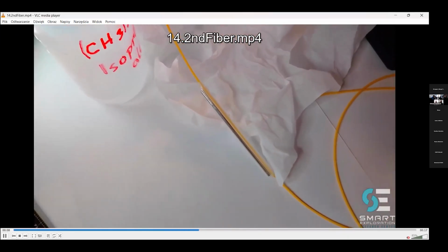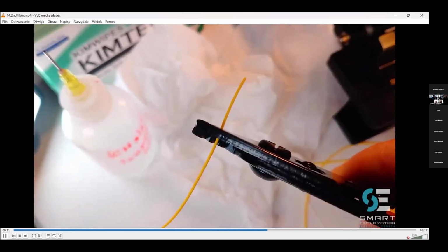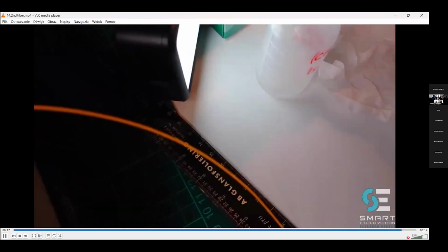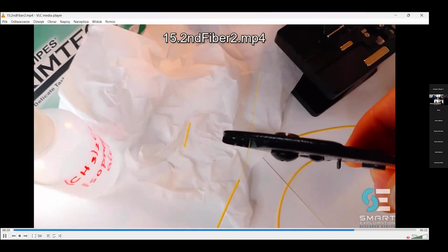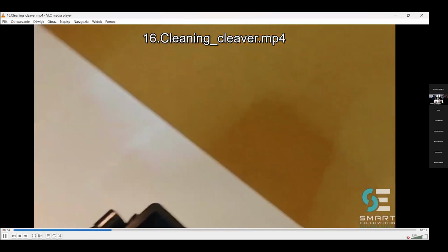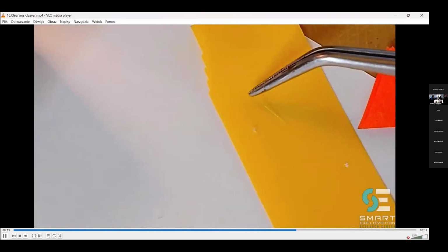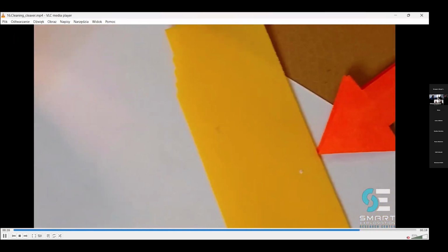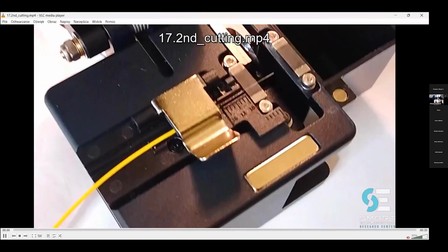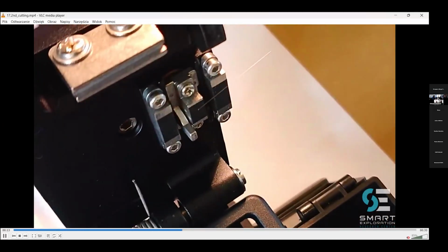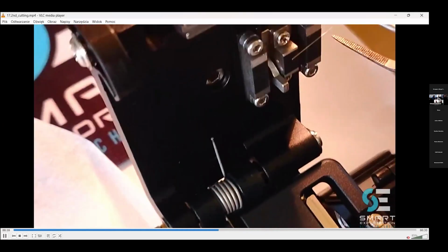And for the second part of the fiber optic that we want to splice with, first we have to add some shrinkable tube, and we repeat the operation with the cladding. And the very important thing is we have to remove our cut-off piece of glass. I very often use duct tape or some strong tape for sticking this piece, because it can be flying away somewhere, or we can accidentally touch it and put it to our skin. We have to be very careful about this piece.